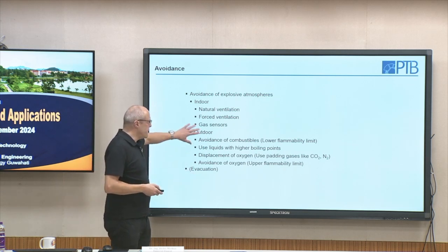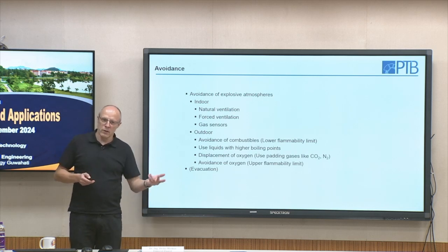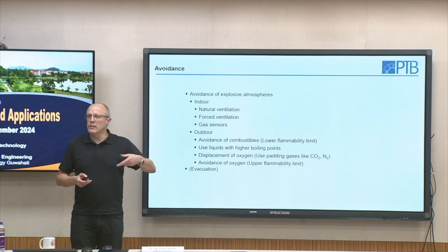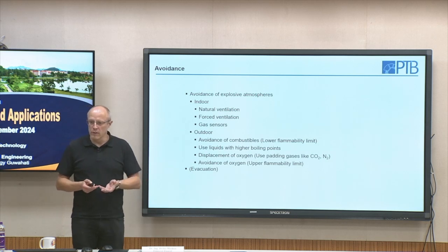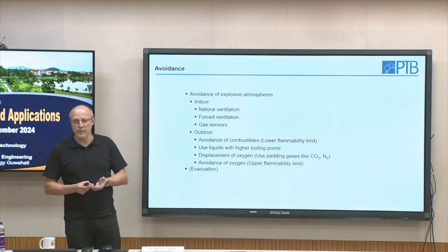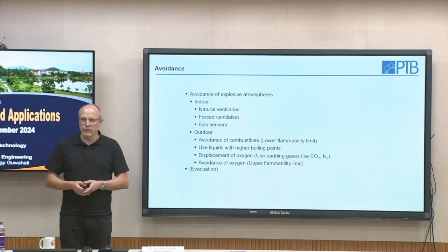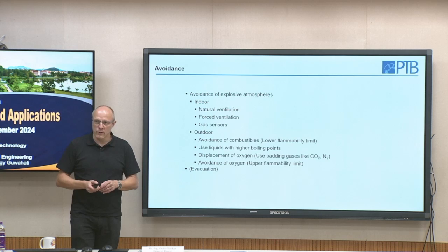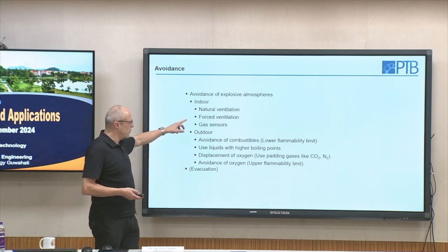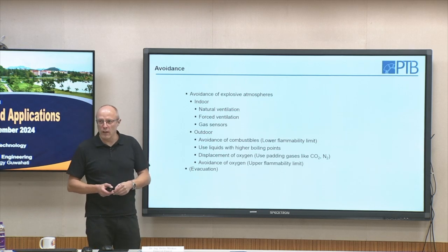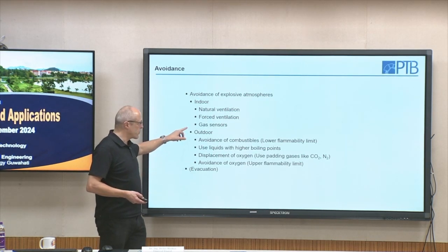And these gas sensors realize, quite below the lower explosion limit, that there is a leakage of whatever, and they give a warning, and after this, if there's still an increase visible, they shut down the whole lab, for example. So all the electricity will shut down, and everyone has hopefully had enough time to leave the area, and firefighters can come and check.